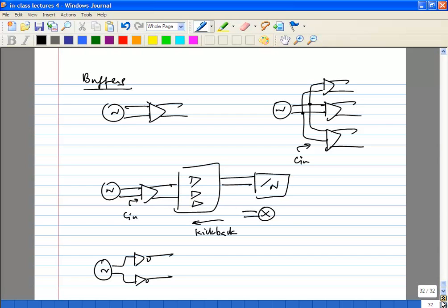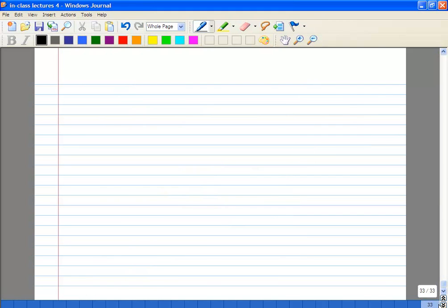So you can do this. The only thing you have to worry about with inverters: they are actually very low noise, definitely there's no doubt about it. Inverter noise, the in-band noise, especially the 1 over f flicker noise area, will be much lower than the VCO, 20-30 dB lower, so you don't have to worry about it. But obviously thermal noise will start mattering.